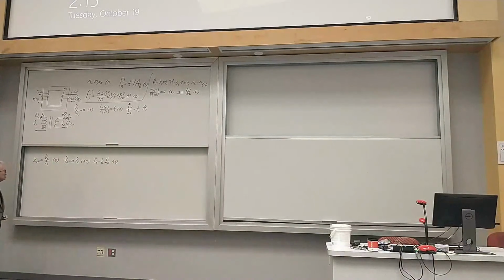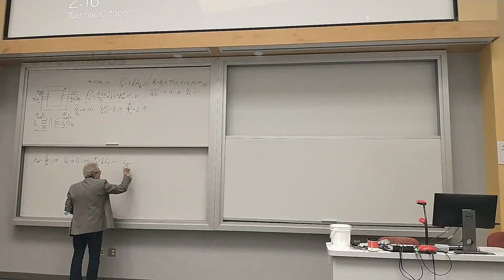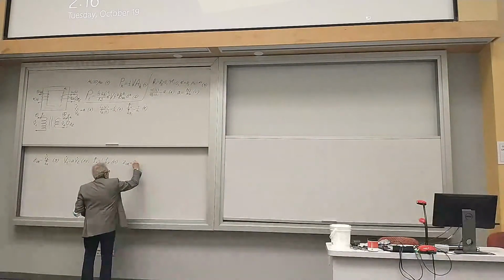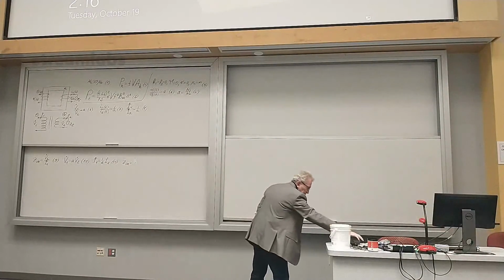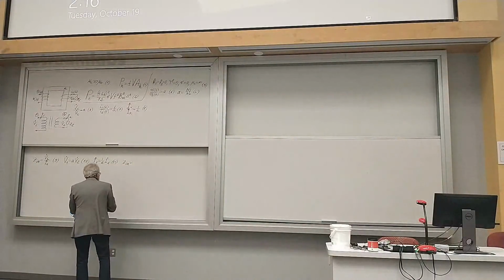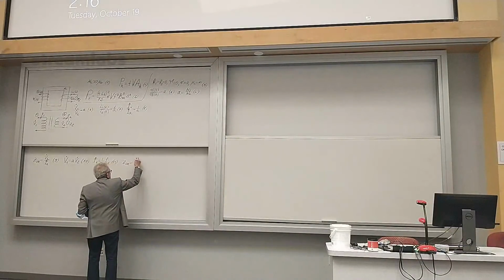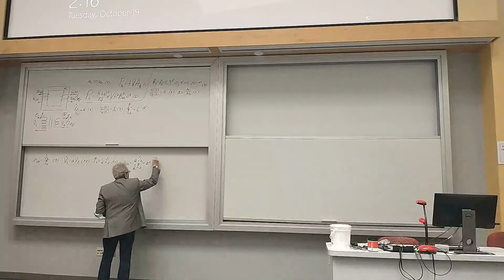Then I will substitute formulas 10 and 11 into formula 9, and I will get that the input impedance will be equal to A times V sub 2 divided by 1 over A times I sub 2 phasors. All this will be equal to A squared, and the ratio of these two phasors, V sub 2 and I sub 2.